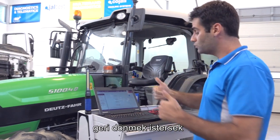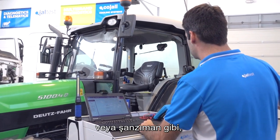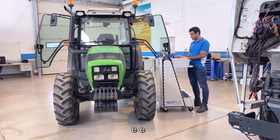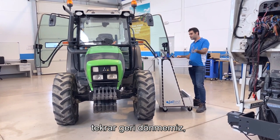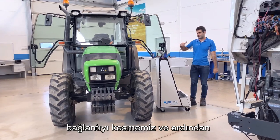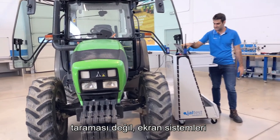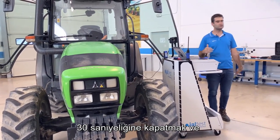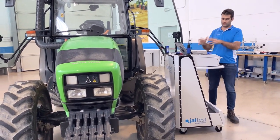If we want to come back to one of the rest of the systems, like the instrument cluster or the transmission, I cannot come back by pressing E several times. Unfortunately, we need to disconnect and then do the display system scan OBD again. I mean, turn the key ignition off for 30 seconds and then select the system we want to connect.